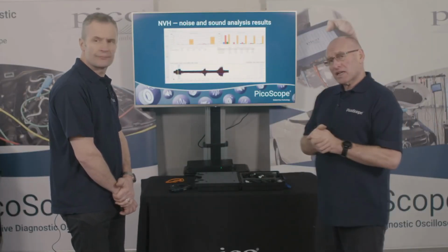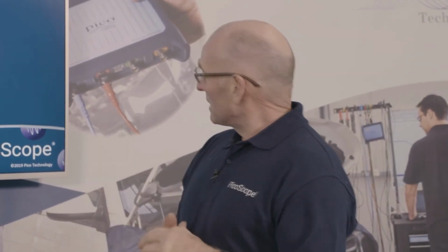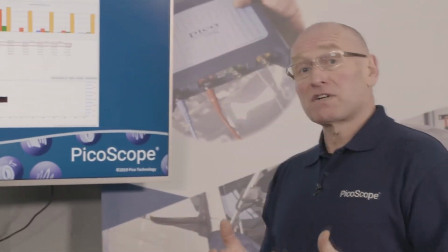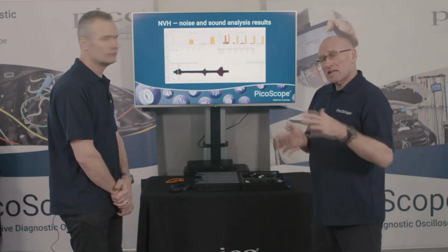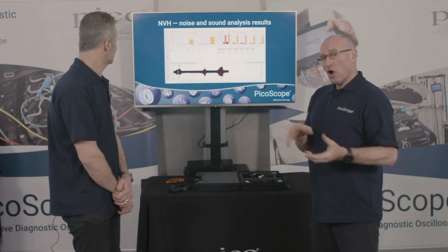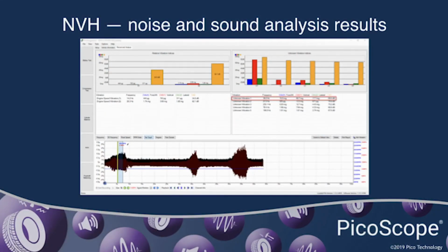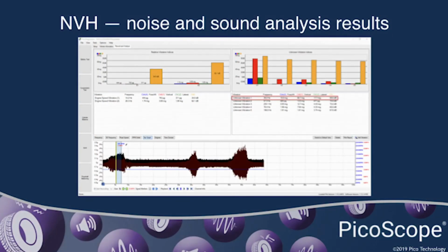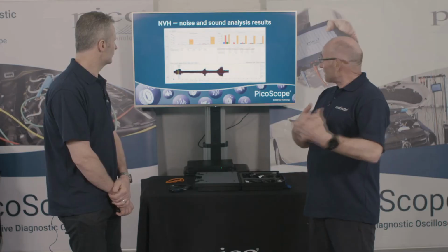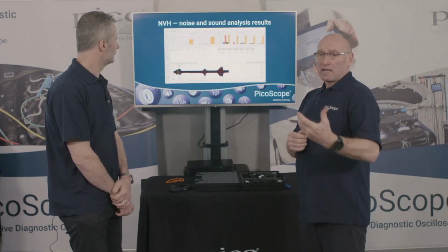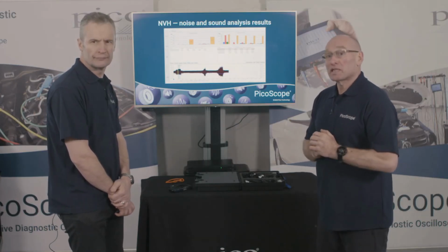I think the really interesting thing I've picked up from this bar graph is that we can clearly see on the right-hand side that this frequency of around 35 Hertz sits quite nicely between E1, E2, so we know it's not the engine. And I think the way I'm thinking at the moment is, if we increase the frequency of the engine, there could be a situation where we get resonance, where we get two forces out of balance which add together. But looking at it in this way, we're able to separate this issue and see very clearly that this is a non-engine related component causing this problem.